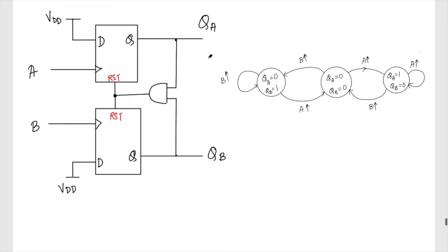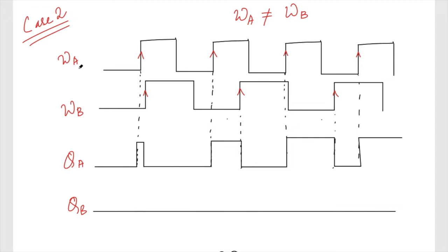Okay, so this digital pulse we want to convert into an analog voltage, because ultimately we'll apply that voltage to the VCO, just like we have discussed in the case of the type 1 PLL. So we can see here that omega A is higher than omega B. So what I am supposed to do now is increase the oscillation frequency of the VCO, and this we can do by increasing the control voltage. So if there are a lot of high pulses for QA, then I should increase the control voltage of the VCO. This is what we will do with the charge pump.